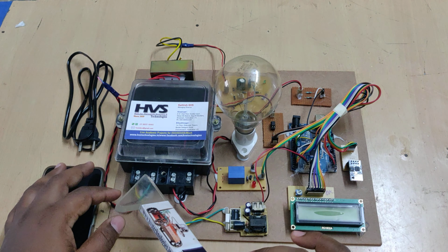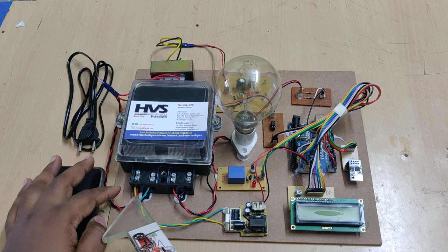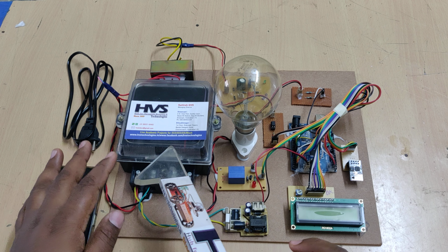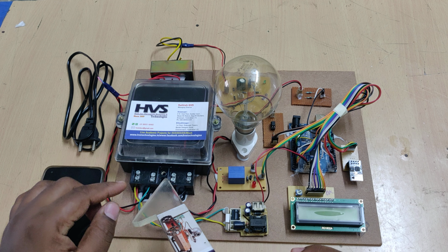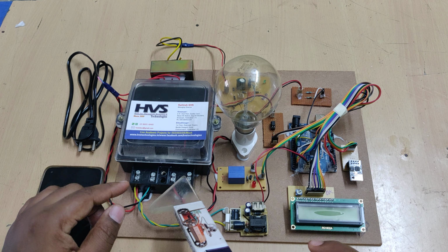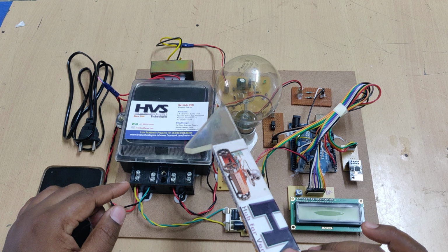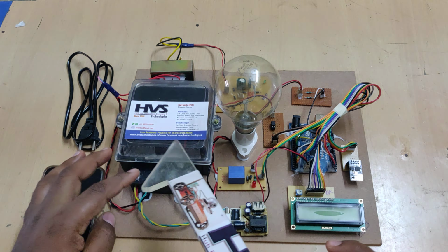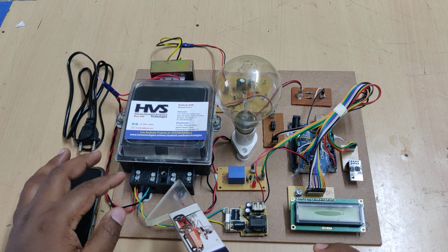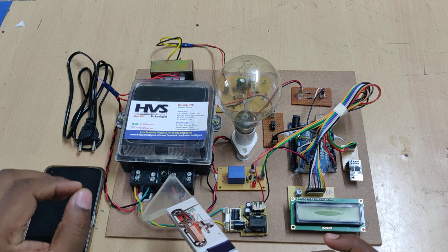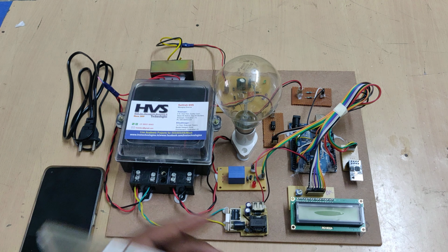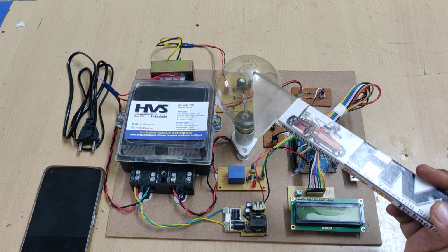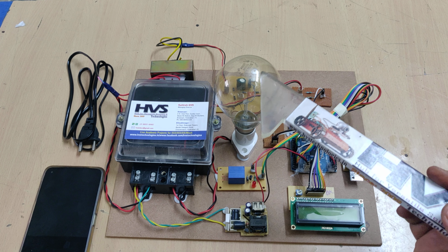And coming to the power consumption of the current rating, this is the input to the current sensor which is inside this meter circuit, and in series we are providing that to the load through the electromagnetic relay, meaning 230 volts AC goes to the relay through the CT, and the CT should be connected in series. Then only we can measure the wattage of the load which is connected in series to the CT.